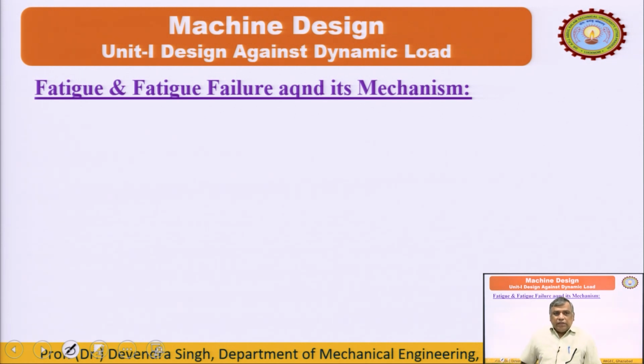Fatigue is the incapability of a material to take further load. किसी भी मटेरियल में अगर आगे कार्य करने की या लोड लेने की क्षमता नहीं होती है तो उसे बोलते हैं मटेरियल इज अंडर फैटिग. And fatigue failure: if a material is subjected to fluctuating stresses, the material fails even below the ultimate tensile strength,